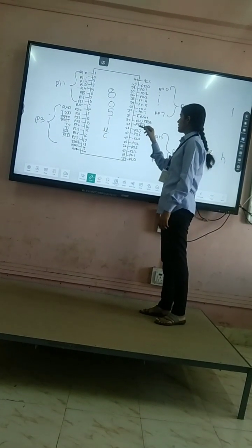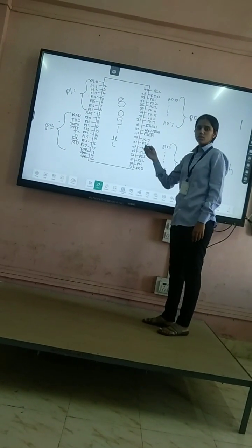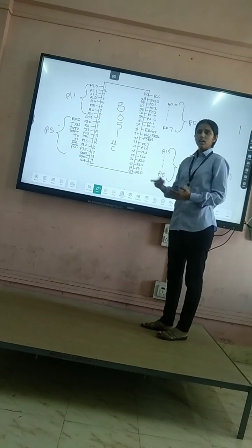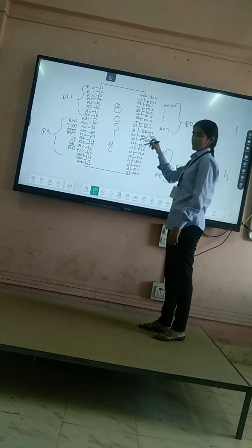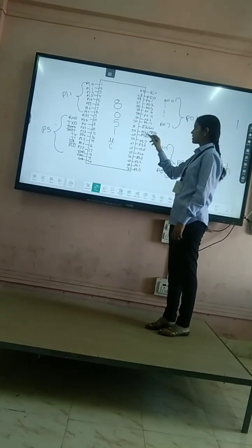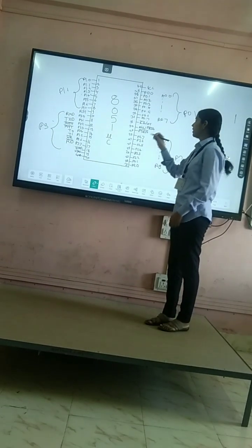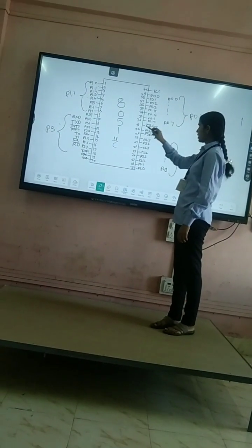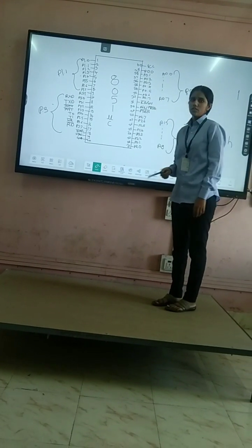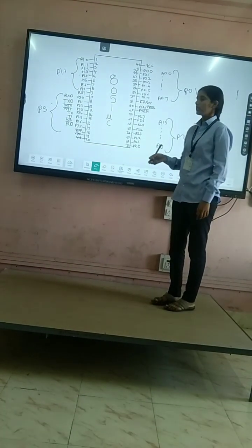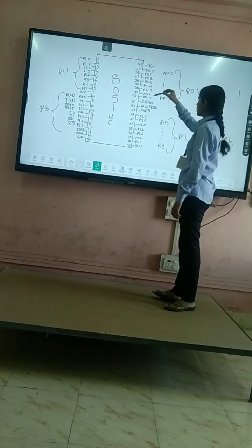Pin number 29 is the PSEN pin, which stands for Program Store Enable, which is used to read signal from external memory. Pin 30 is ALE, which stands for Address Latch Enable, which is used to demultiplex the address and data bus. Pin 31 is EA, which stands for external access, which is used to enable or disable external memory interfacing.